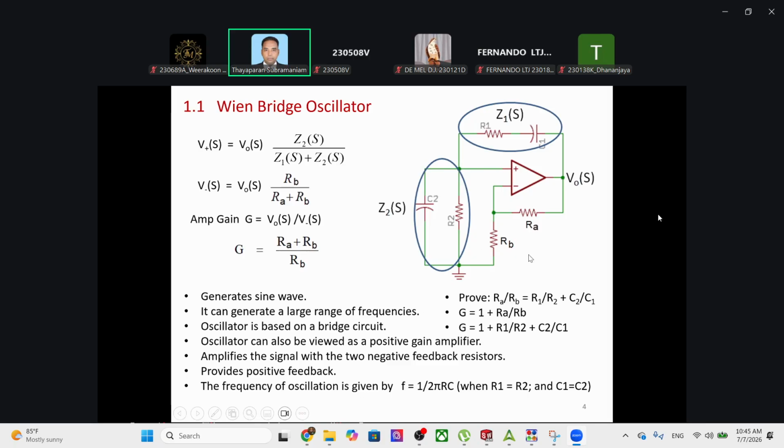So we have some additional points today on how to do the lab. And also, what would you do if you want to increase the frequency to the maximum frequency? If you look at the equation, f is equal to 1 over 2 pi C square root R1 R2, you can bring the C down. That means when you reduce the capacitance, the frequency will increase. But again, with some limit, it is difficult to go beyond certain limits because of the parasitic capacitance; we are using standalone components with high tolerance. Therefore, parasitic values will have some effect.